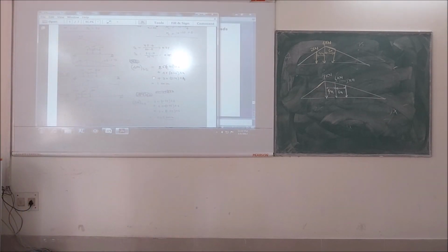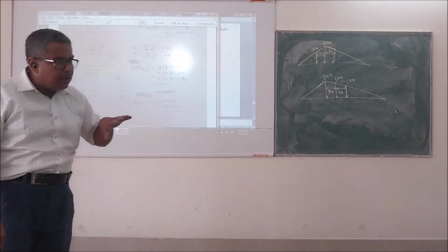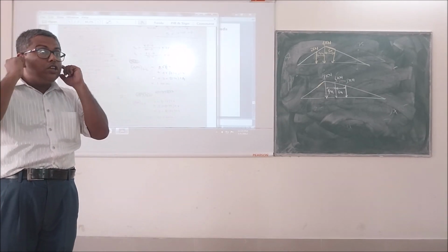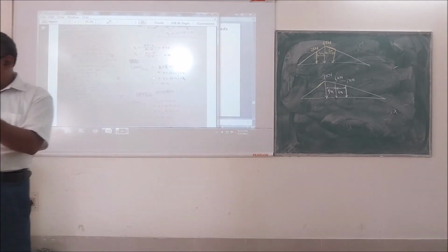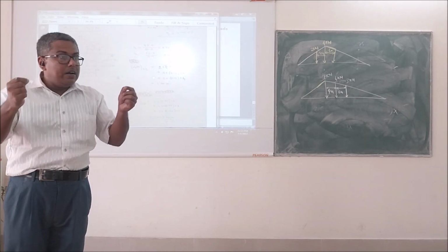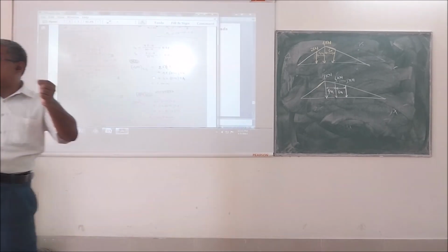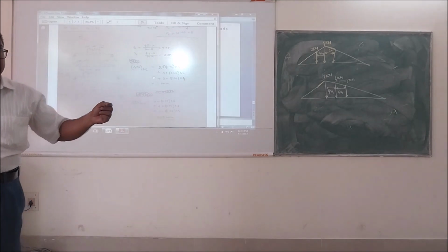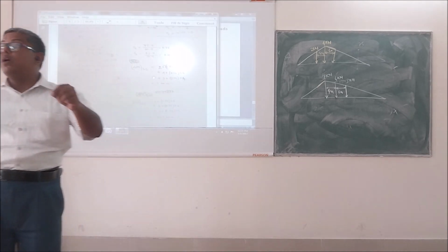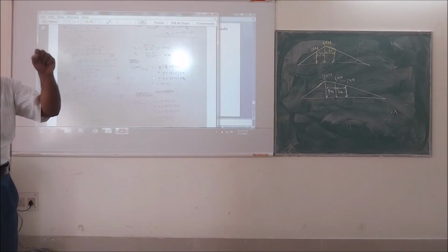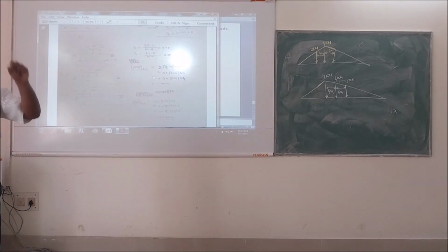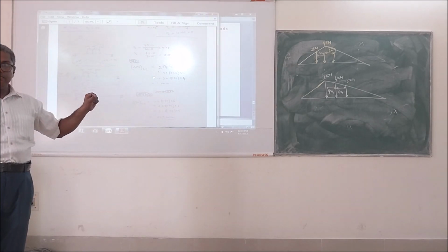But when the loads are separated by different distances, the confusion will come. But one thing you should understand: whenever there is movement of the load, it is not that the axle is moving or the position of the loads is changing. Position means two wheels are not coming close to each other. It cannot come. What is happening? The position of the load is changing depending on the front load movement. And the position you are considering depends on the case which will give you the maximum value, when the concentrated load will be positioned at the maximum ordinate position. Is it clear?